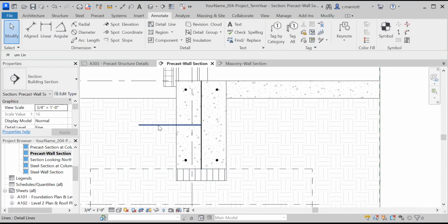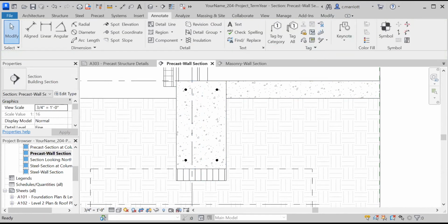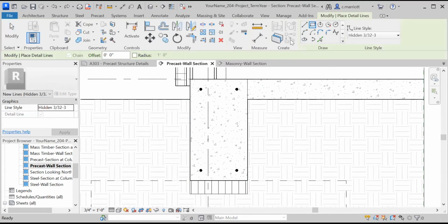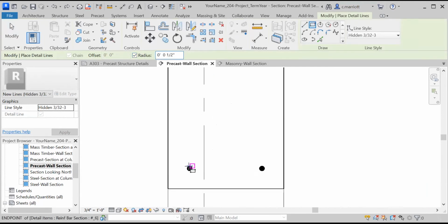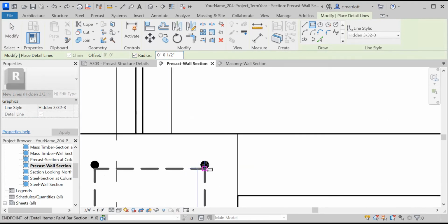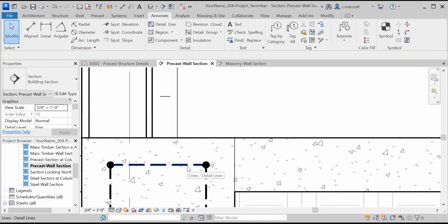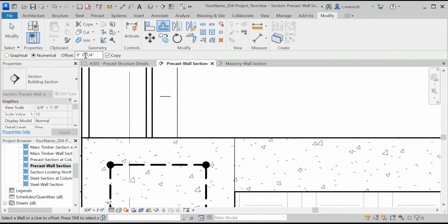There it goes. Rectangle. For the radius, I'm going to input 0.5 inches. And then I'm going to snap to those centers. And then I will use the offset tool. The offset distance will be 0.5 inches. Pick that.